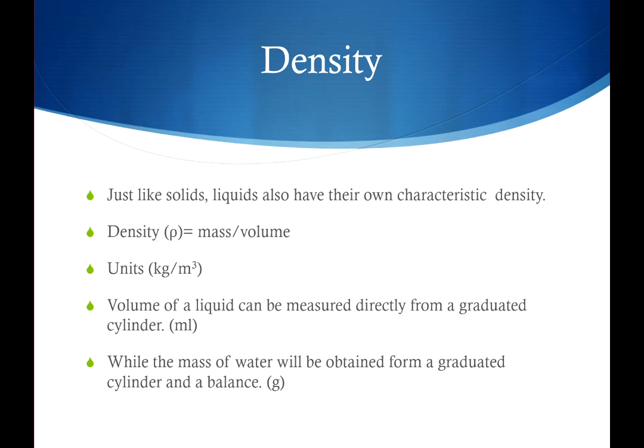In the cylinder we have both the weight of the cylinder itself and the weight of the mass of our sample. The density of the test fluid is to be found by weighing a known volume of the liquid using the graduated cylinder. The cylinder is weighed empty. Then it is filled to a certain volume according to the graduations on it, and it's weighed again. The difference in weight divided by the volume gives the weight per unit volume of the liquid. By appropriate conversion, the liquid density is calculated. The mass per unit volume, or the density, is thus measured in a direct way.